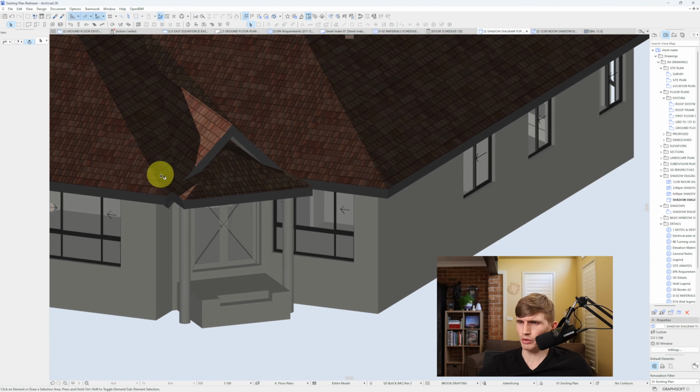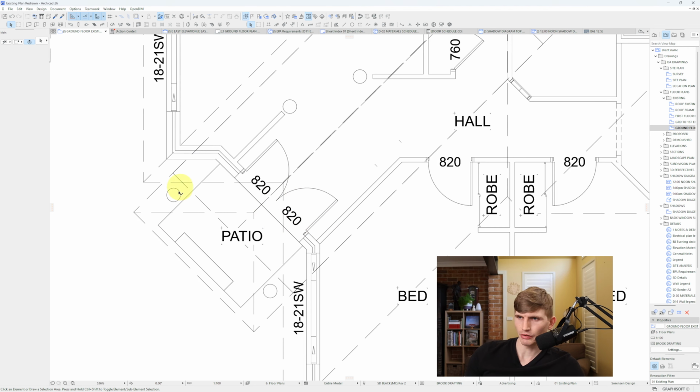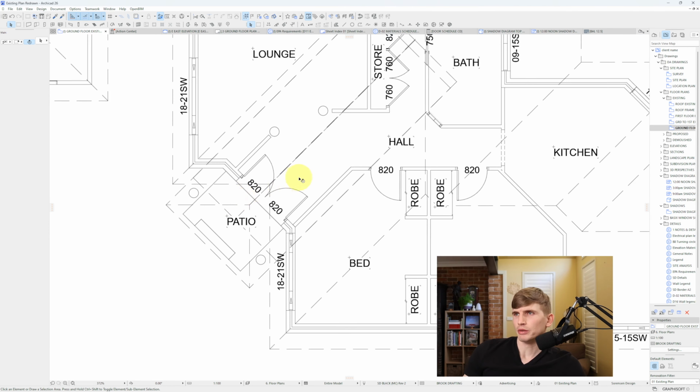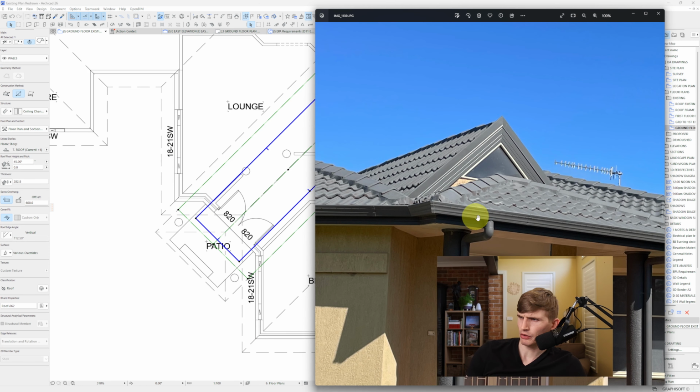Okay, so next up we'll want to create a wall just in behind and a little highlight window. So let's go back into our floor plan. Lots of lines going on here at the moment. So what I'd probably do in reality, I just put this so it's just on the roof plane, so it's not distracting from the actual floor plan itself when we're trying to actually design. Just looking at my reference, it looks like this wall lines up with this one just here, and the actual face of this all lines up with the wall as well.